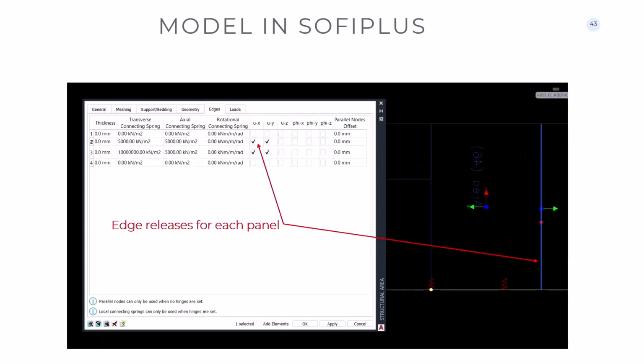The most interesting for us, and the one that we are using more and checking more now, is that in previous modeling, we manually split each panel with a gap of 5 centimeters. In every single real splice, we had to make a cut of 5 centimeters, and then each node of the left part connected to the node of the right part with a spring.